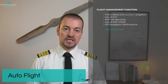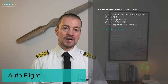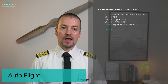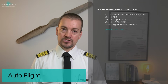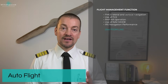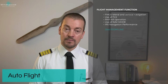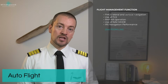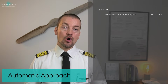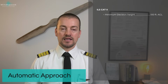For use of the FMS landing system, the FLS approach, this is part of the PBN approach capability. RNP AR operation, use of NAV mode in normal operation and for IRS navigation performance. Check your FCOM limitations chapter for more detail on the flight management function limitations. The automatic approach capability is also part of the autoflight limitations chapter.